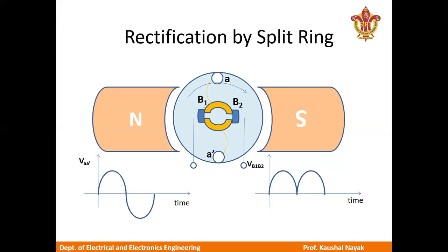The stator of the DC machine carries salient poles, which produce a stationary air gap flux. For the development of electromagnetic torque, the armature MMF wave must also be stationary in space. The commutator in a DC machine carries out this second important function of rendering the armature MMF wave stationary in space in spite of armature rotation.